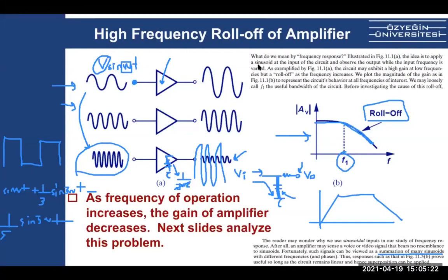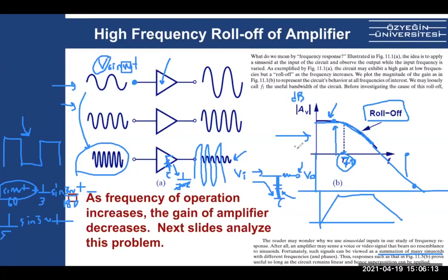So that means your circuit, for instance with this square wave, at the output maybe will get this, right? Because you have a gain of AV, but if it's a very high frequency signal, let's say this is 60 gigahertz, and let's make this 70 gigahertz, okay? For a 60 gigahertz signal you'll get gain AV, but for 3 omega, 180 gigahertz, somewhere here, the gain is much lower. This axis is in dB, so this is 0 dB, which means you multiply with 1.